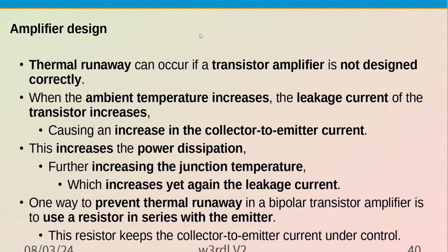Okay, thermal runaway. It's not something you worry about with the vacuum tube amplifier. But it's the solid state problem. I think I mentioned the fact that with an increase in current, it heats up and resistance increases. Take an old style light bulb. If you measure it with an ohm meter, it's very low resistance. So then you put 120 volts on it, and that filament starts going, it increases its resistance.